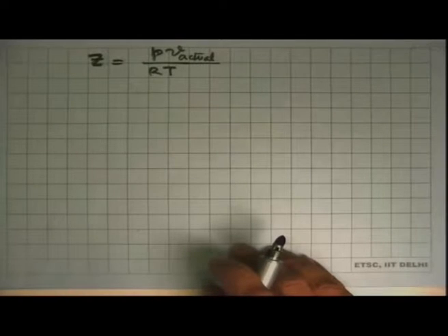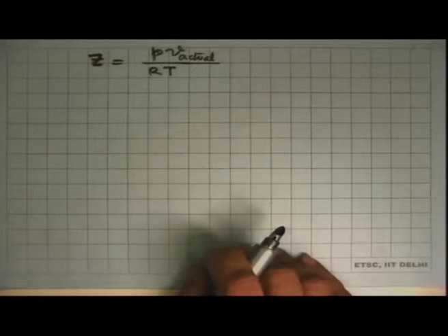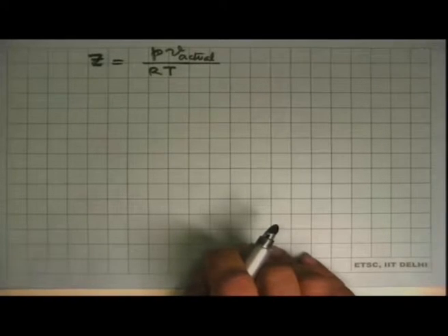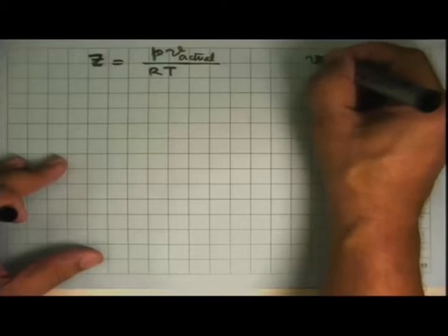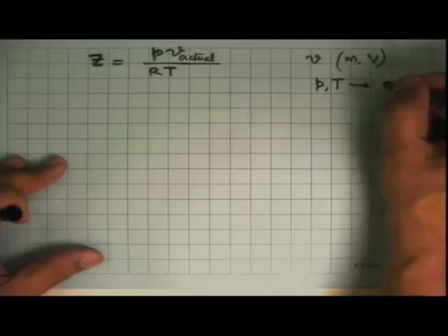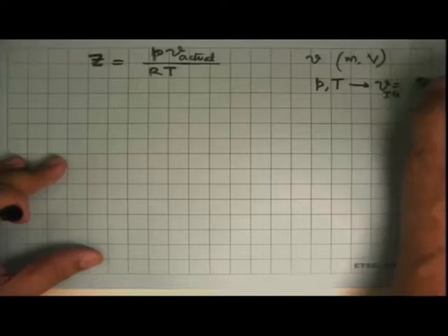That means your medical oxygen cylinder at home, it has got a certain specific volume. We know the pressure and temperature at which it exists. So the actual specific volume we know because the mass and the volume of the cylinder were known. Independently, we know the pressure and temperature, and ideal gas equation of state tells you that V ideal gas is equal to RT upon P.